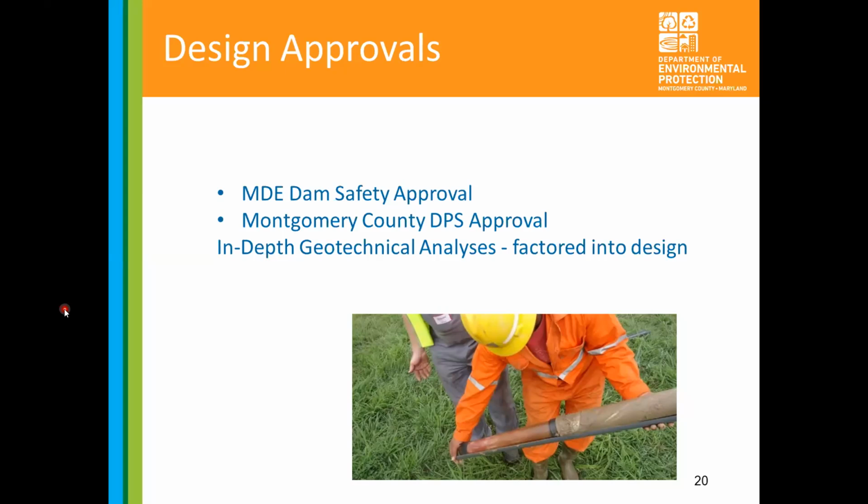It is currently under review for permitting with Montgomery County for erosion and sediment control measures during construction. That way, when they dig up the dirt to put in the gravel, there's not going to be any sediment entering downstream.